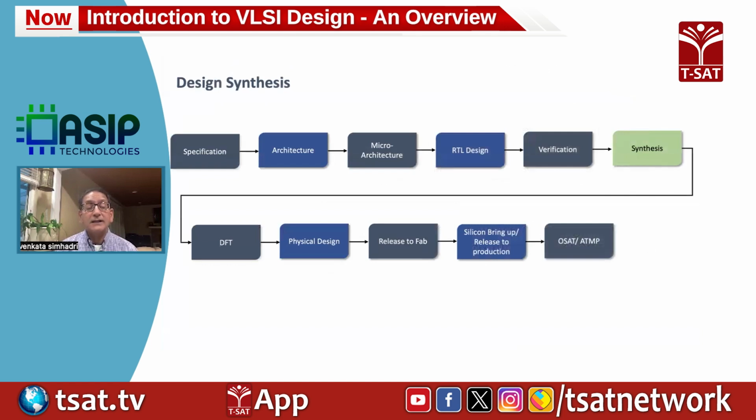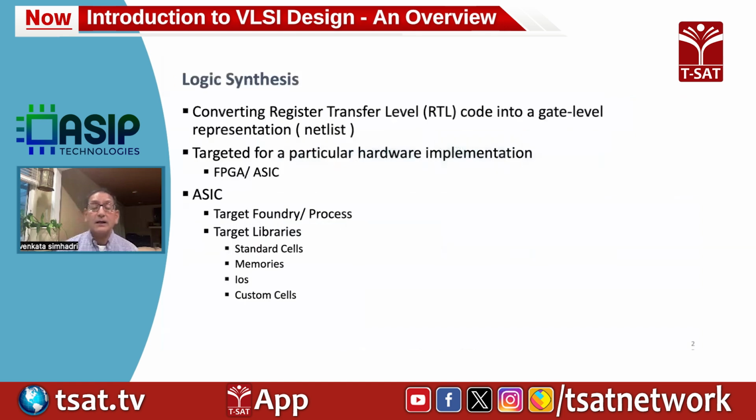And the next step after the RTL design is done and verified, it meets your functionality and meets your spec, then you have to convert that into a gate level netlist. That is called synthesis. So we'll get into a little bit more detail about what this logic synthesis is all about.